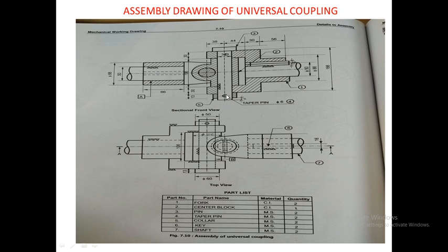This is the taper pin which will be inserted inside the vertical pin, and this pin is having its top view here. You can see these two dotted lines, from here to here and from here to here. These two vertical dotted lines is nothing but the top view of this taper pin. Now they are dotted because this pin will not be visible from the top view. So this is the top view of the pin which is inserted inside the vertical pin. Now why this pin is used? This pin is used to lock this vertical pin with the fork and the center block.